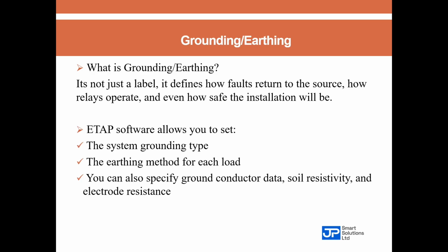The first thing they do is build their single line diagram, and once you're done with your single line diagram, you carry out, of course, a load flow study, because load flow study validates your project model, which is your single line diagram. So once the single line diagram is built, you start running your studies, your load flow, your short circuit, and you assume that ETAP's default grounding is good enough. But that single assumption can alter everything that follows.